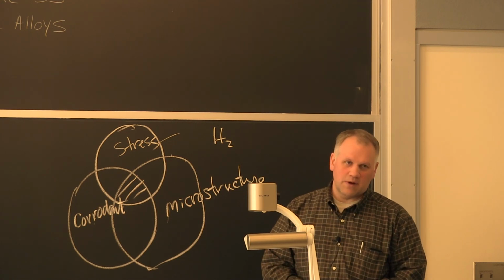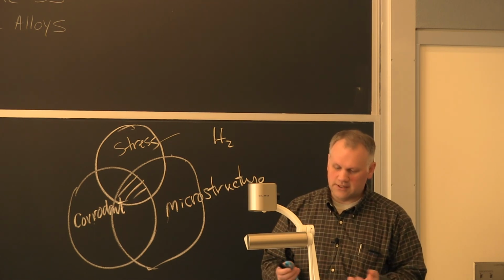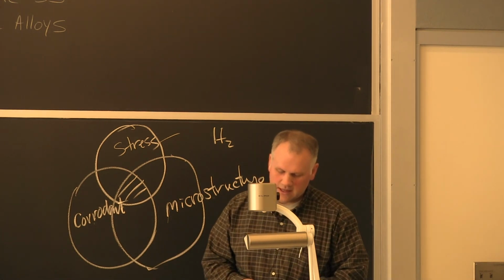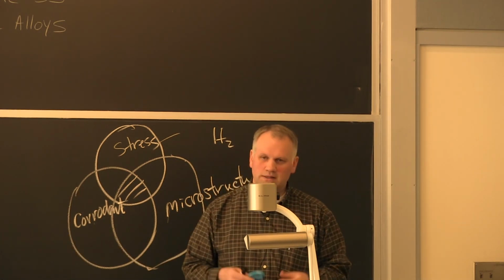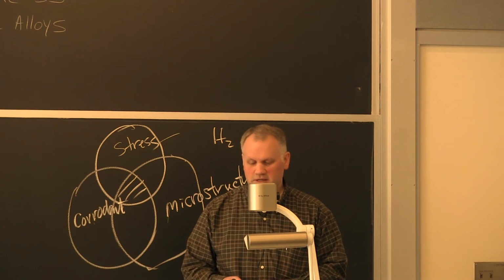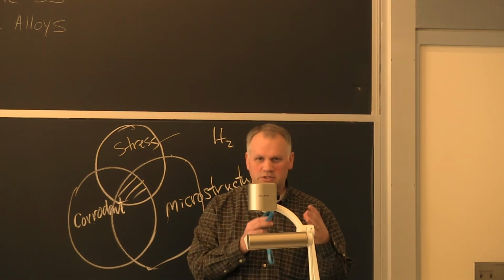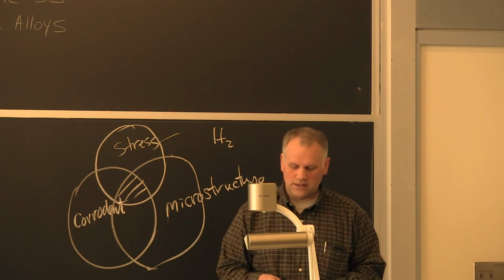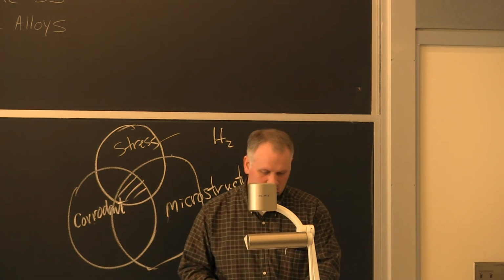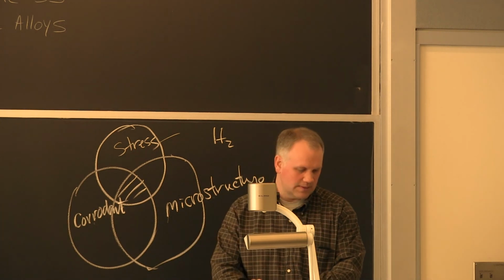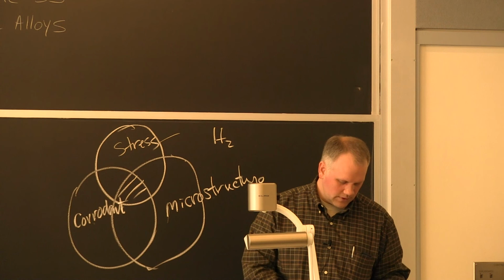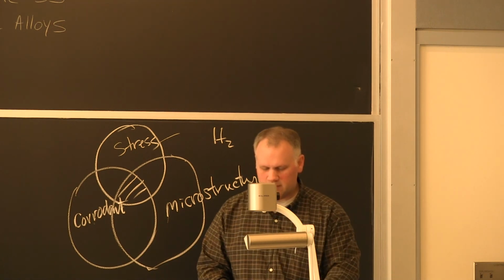And another thing to keep in mind, especially if you're welding nickel-base alloys, is most nickel-base alloys have not been developed with welding in mind. They've been developed to cast and then machine an airplane turbine or something like that. And welding was not always kept in mind as they were developed. So because of that, we do end up with some weldability issues.